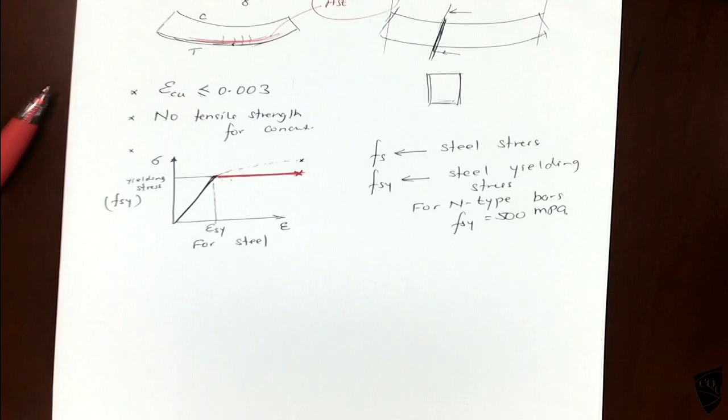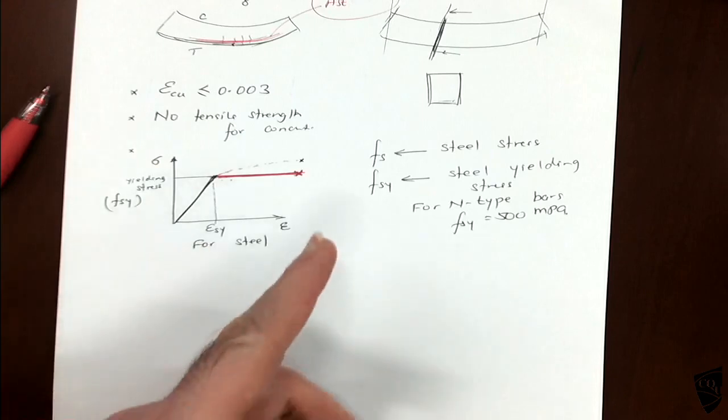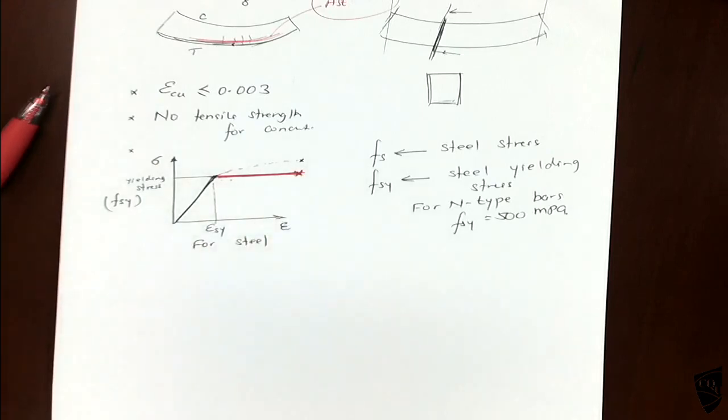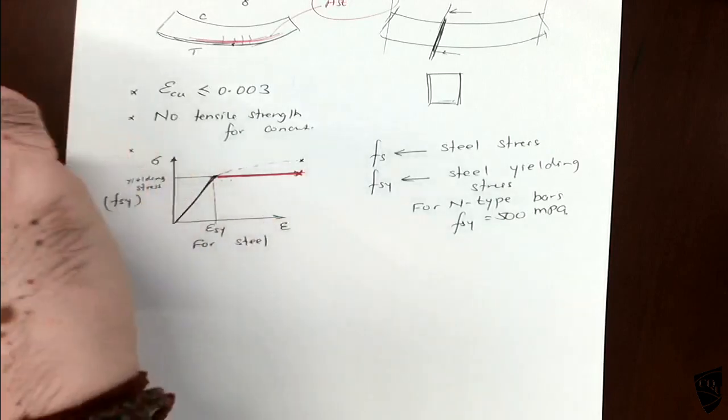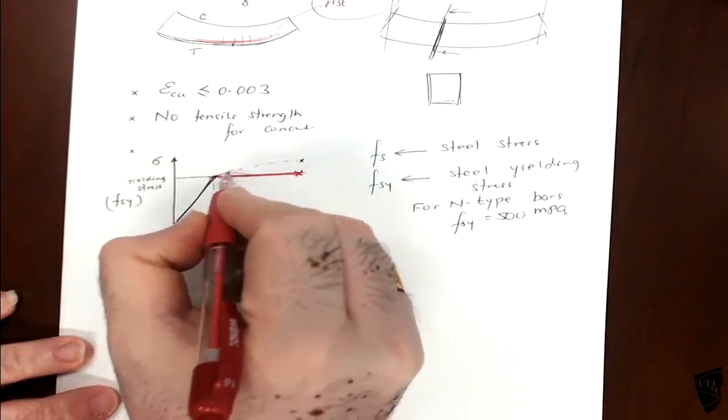But reinforced concrete bars normally have good ductility. So we need good ductility so that we know the beam has reached the yielding point and is expanding. It is quite dangerous if it expands too much, because it will fail. So we like to have the design somewhere within this region.